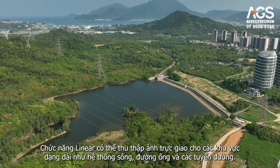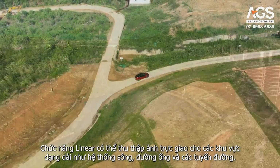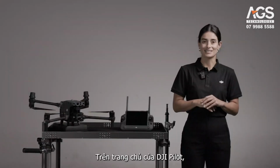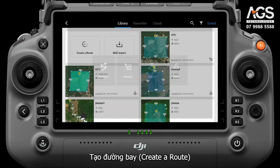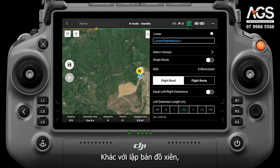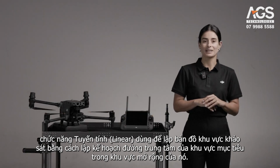Linear function can collect orthophotos for belt-shaped areas such as rivers, pipelines, and roads. On the home page of DJI Pilot, click Route, create a route, and select Linear. Different from mapping in oblique, linear is to map the surveying area by planning the center line of the target area and its expanding area.